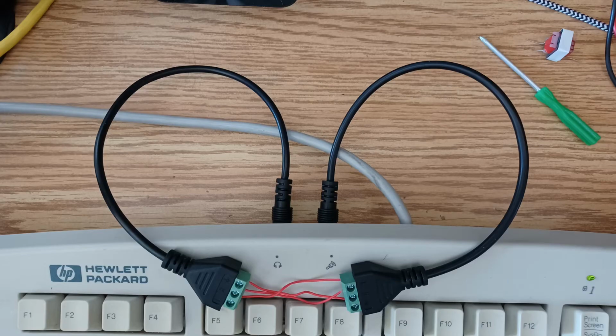So the first step to use this software, you need to calibrate your sound card, and in order to do that, you need to connect together your input and your output, like a kind of crossover, like I've done here with these two short leads. I'm lucky my keyboard has an extension from the sound card coming out in the back of my computer. So that comes directly into my keyboard, and the keyboard has two jacks in the back where you can plug these short leads.